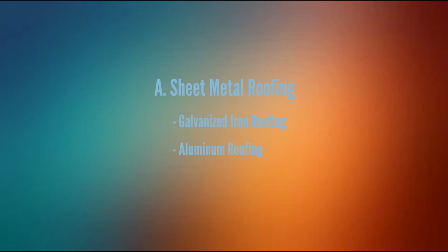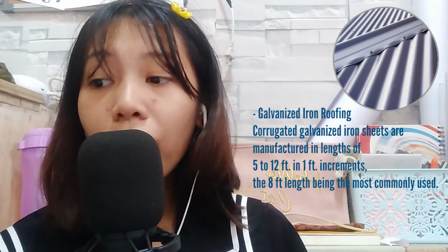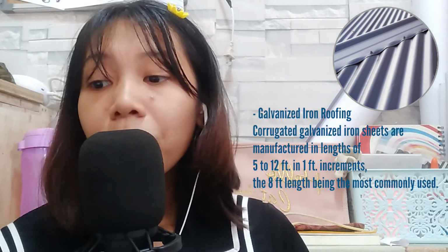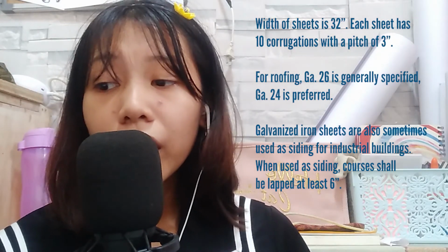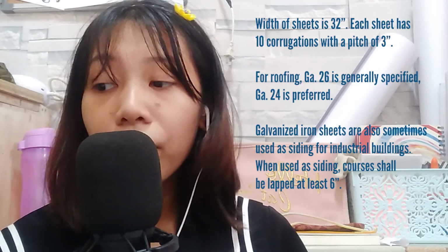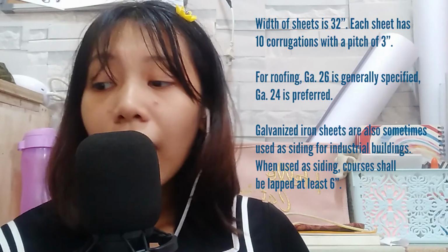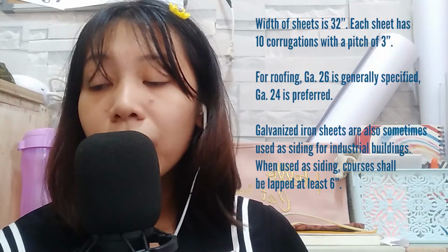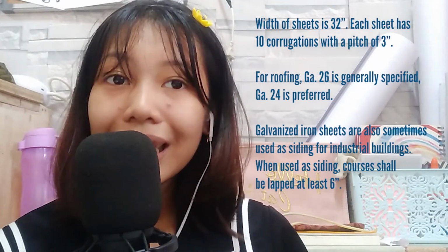Under this category falls the galvanized iron roofing and the aluminum roofing. So corrugated galvanized iron sheets are manufactured in lengths of 5 to 12 feet in 1 foot increments, with the 8 feet length being commonly used. Width of sheets is 32 inches, and each sheet has 10 corrugations with a pitch of 3 inches. For roofing, GA 24 is preferred. Galvanized iron sheets are sometimes used as siding for industrial buildings, and courses shall be lapped 6 inches.